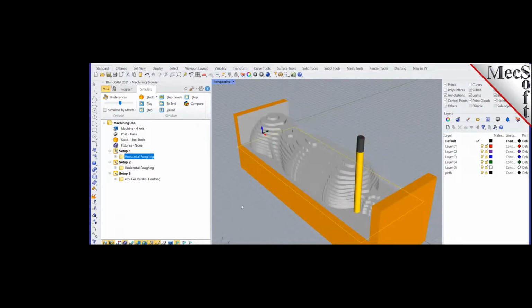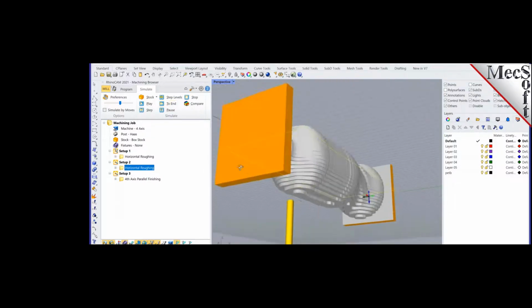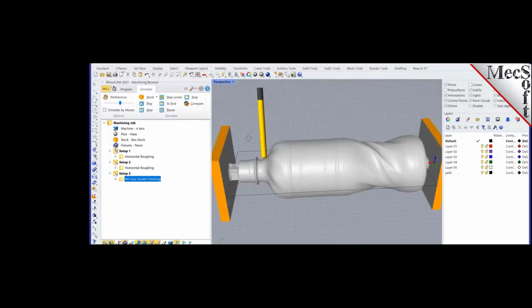Okay, there you go. That's the toolpath from the top. So you did a roughing, and then we did that to the bottom. So there's your model roughed out. And then next you can run the parallel finishing toolpath. Okay, so that to end. And you can go along or across, and then also do helical patterns. If you want to do a helix, you can do helical patterns as well. Okay, there you go. That's a pretty nice finish for you.